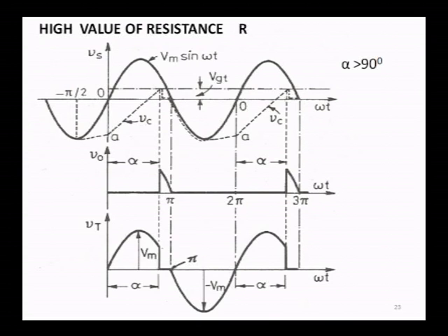You can see here it has crossed the peak value at 90 degree. Now, you can fire this SCR beyond 90 degree. So, this waveform is very important for you, so that this shows clearly that your firing angle has increased beyond 90 degree, and even 0 to 180 degree can be obtained.